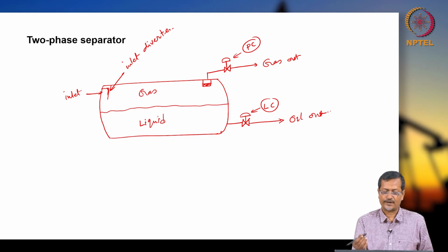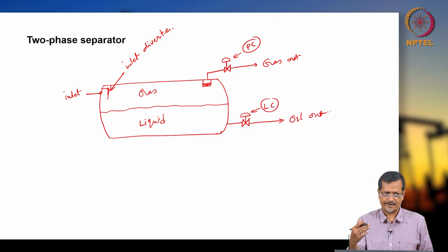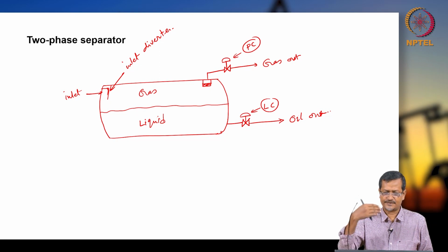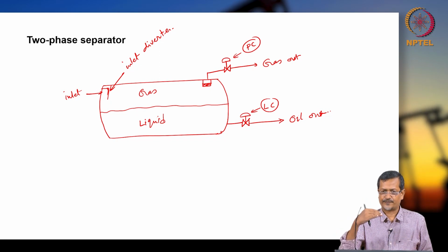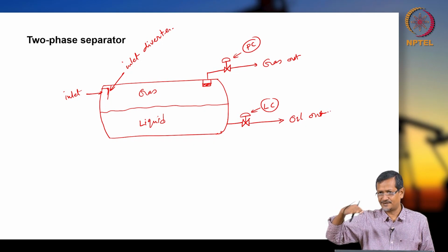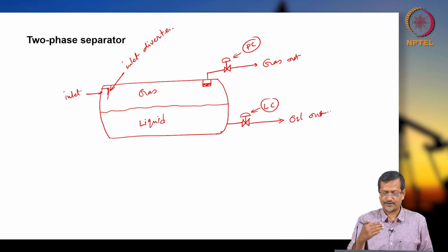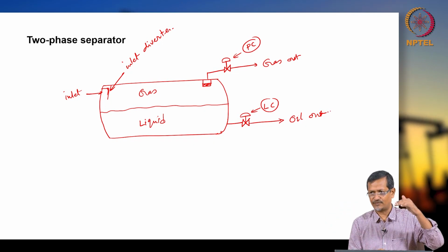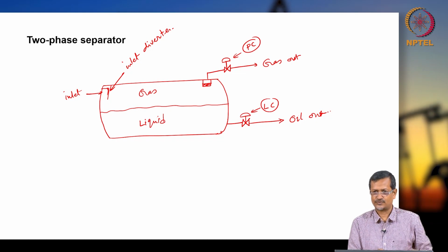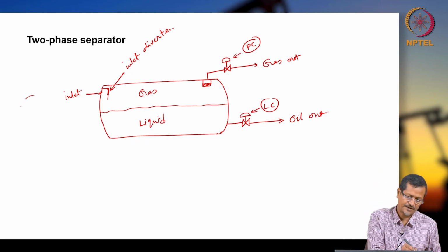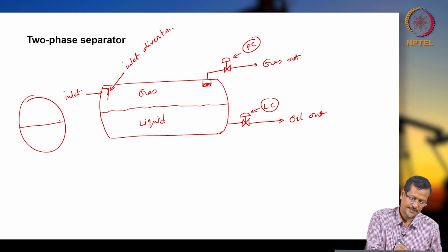Now you are creating 2 layers, and normally it will be 50% filled. If you make it 50% filled in a circular cross section, you are getting more surface area, interface area. If you increase to 60% liquid filled, 40% gas, your actual area is reducing. If you see from the side view, this is the largest area, right?